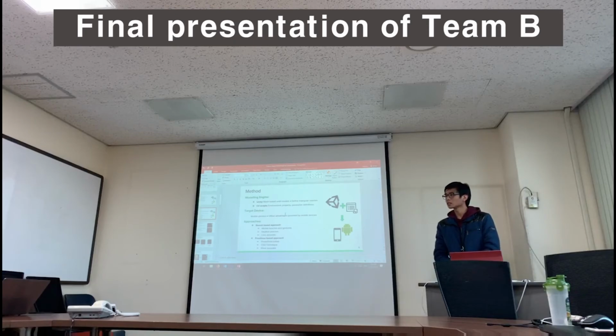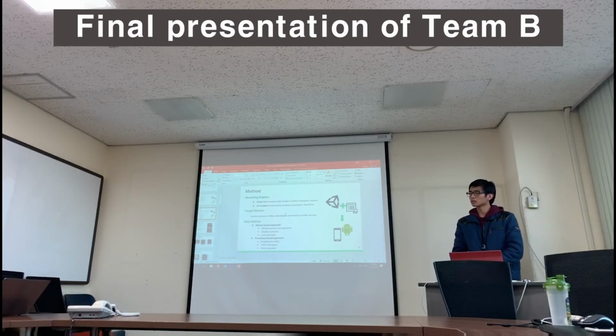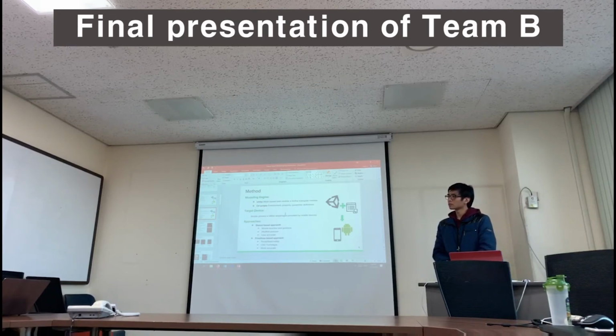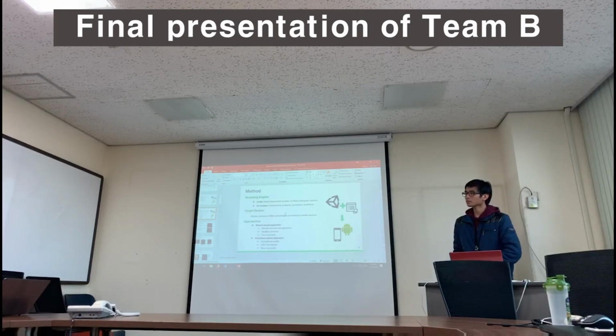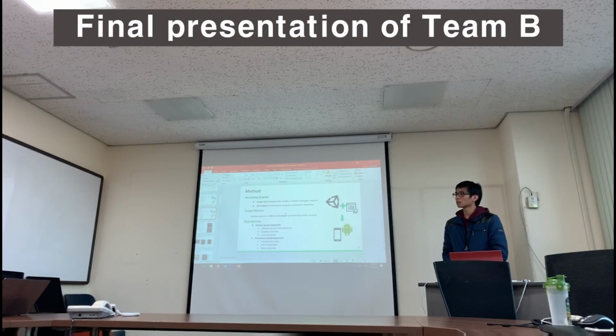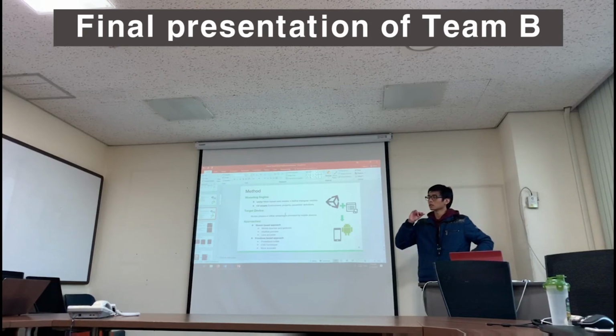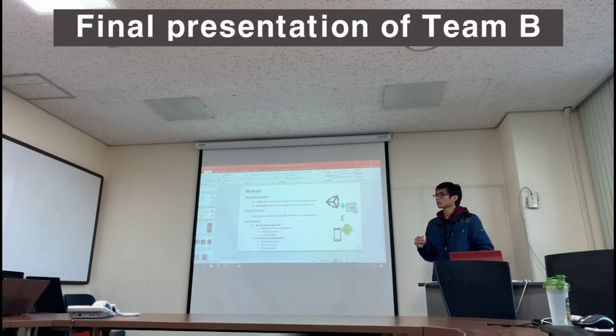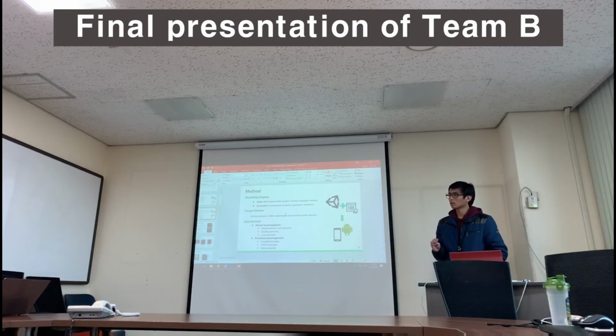Then the data structure is primitive, it is CSG, rather than mesh. So mesh is used only for display. Is it right? In the case of CSG, predefined models are also a mesh. So it displays a mesh, but doesn't store it as a mesh. Storage is only 3 numbers, right?